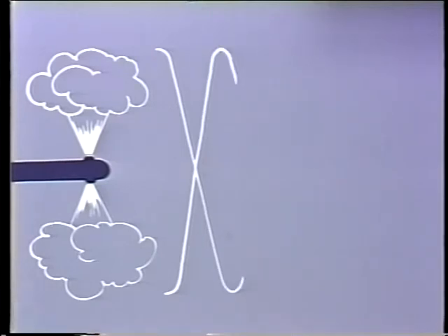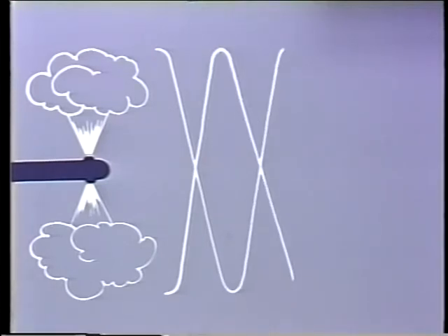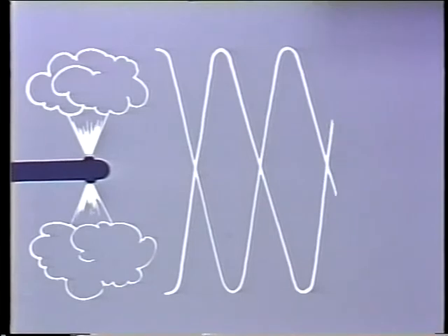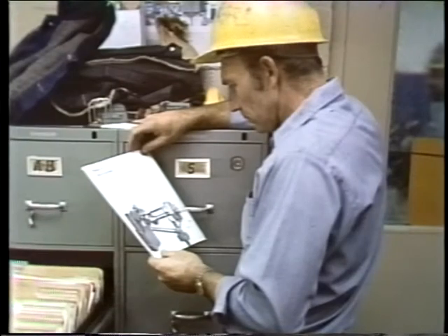Many long tube retractable soot blowers are set up to cycle back in with the blowing medium covering the spaces in between the helical path followed on the way out to provide more thorough cleaning. Details of how this is done can be found in the manufacturer's literature on specific soot blowers in your plant that work this way.